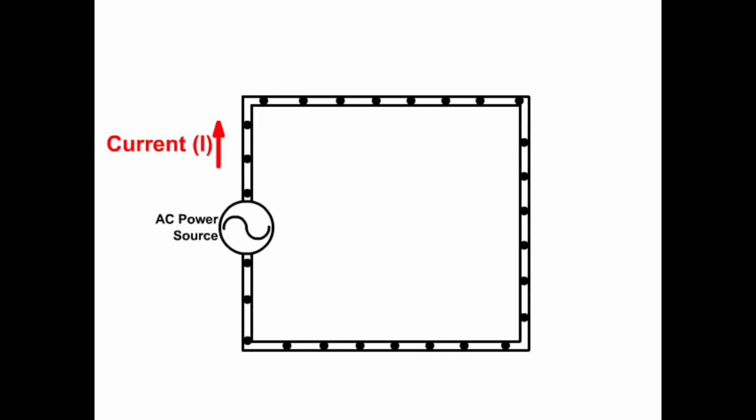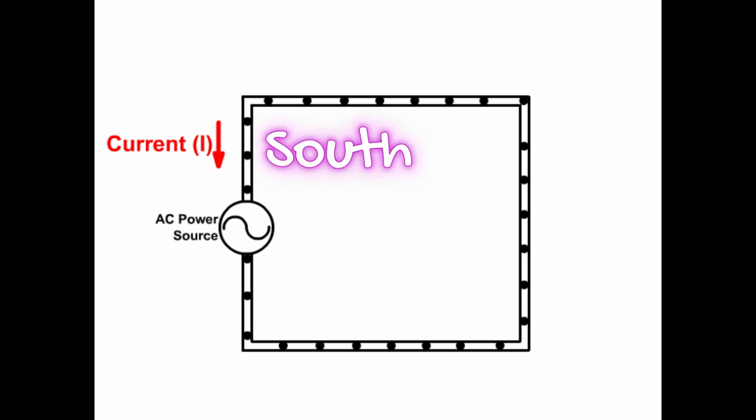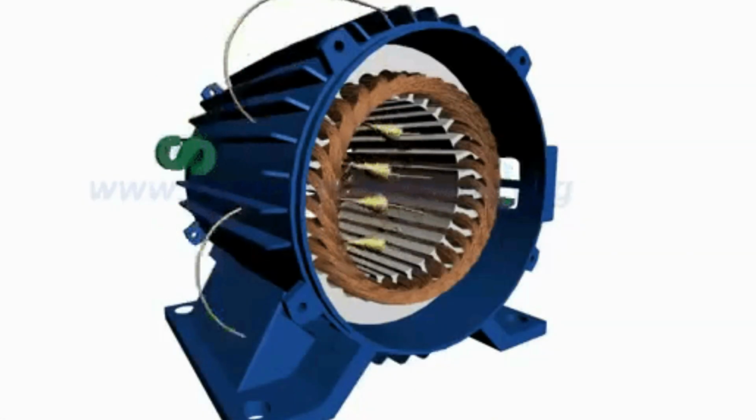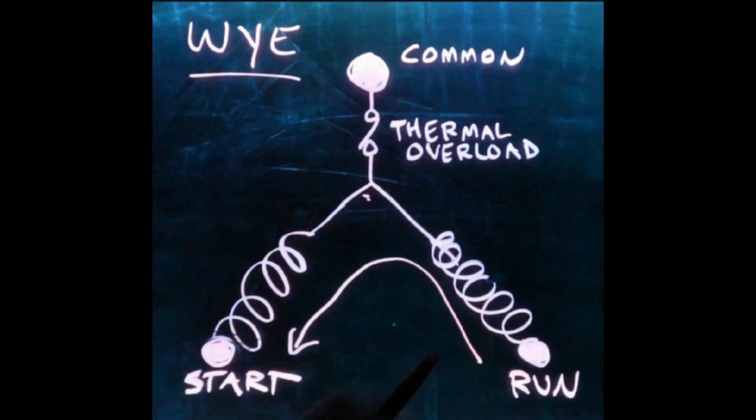So when a current runs through a single winding in a motor, we have a magnetic field that's flipping back and forth in polarity. But this flipping back and forth is a linear pattern. It's not that rotating magnetic field we need to actually spin a motor. Now, residential compressors and other types of motors don't have just one winding. They have two, a start and a run.